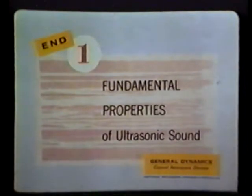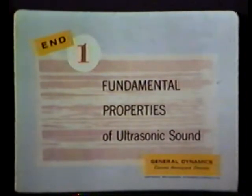Again, wavelength, lambda, is a ratio. The top number of the ratio is a fixed value, this being the velocity, v. The bottom part of the ratio is a variable, this being the frequency, f. For a given ultrasonic test, different test frequencies may be used. And as the test frequency is changed, so is the wavelength. These relationships will be explored more fully in the discussions to follow in Part 2 of this training series.